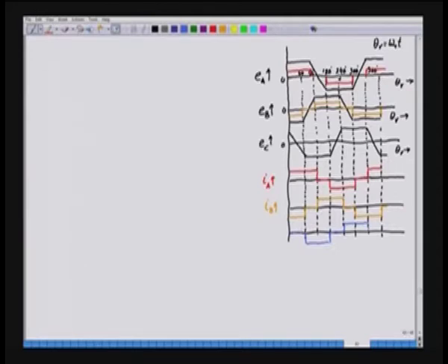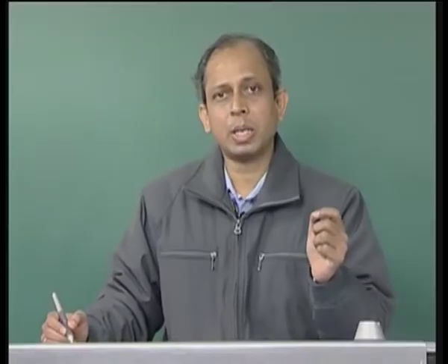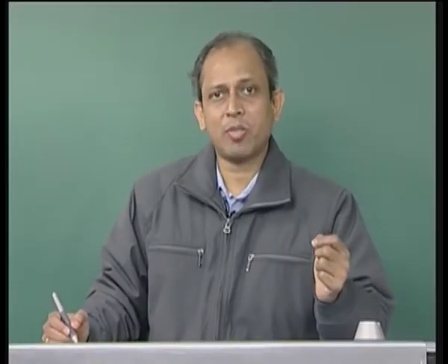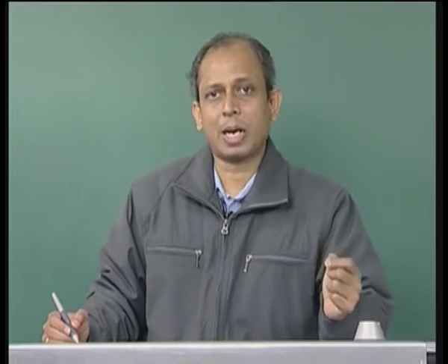And here also we have 0 current, negative current, and this is IC, and we have the origin here, and these are all against theta r, the rotor angle. So, as the rotor rotates, the back EMFs are trapezoidal in nature, and the current which has to be injected into the various phases will be quasi rectangular in nature.